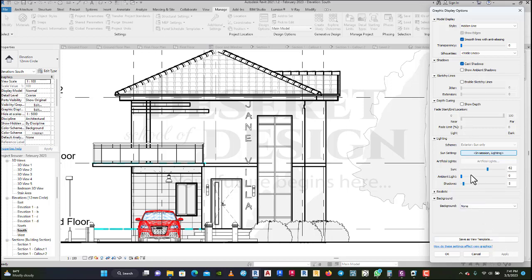Now, all these settings we've done, we don't want a situation where we did it with the front view, and if we want the same thing at the back view, we have to go through the whole process. No. So what we've done here, all these settings, we will save as a view template, so that we have that setting. In any other view, we'll just pick this view template and apply, and all the things we've done will be applied. But first of all, you need to save the view template.